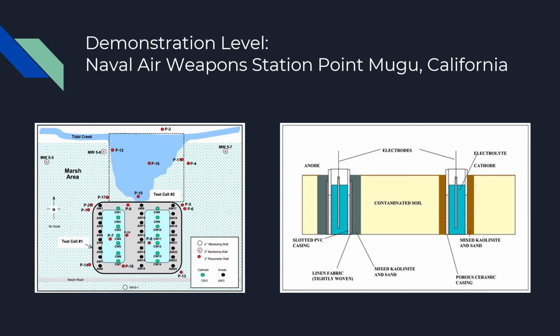The site was subjected to 30 volts and 333 amperes for remediation. Continuous monitoring was performed to check for soil heating. The sensors attached to each cell monitored temperature, pH, voltage, and current. Due to public and regulatory concerns, mineral acids, nitric and sulfuric acids were not used in the site. Only citric acid was used for enhancement since it was available readily, environmentally friendly, and was relatively inexpensive.